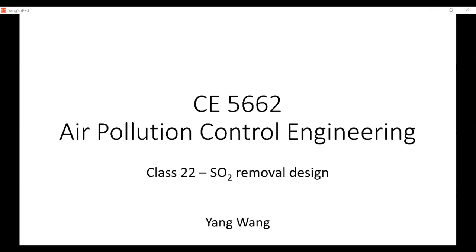One thing I do want to point out is that the pre-cleaner mentioned in the project is the cyclone. Okay? It's not something else. The reason we call it a pre-cleaner is that we don't want to introduce all the particles into the ESP or baghouse. We mentioned that cyclones are low cost, and they can also remove a lot of larger particles. In that way, we can pre-clean the flue gas and then send it to the control devices.